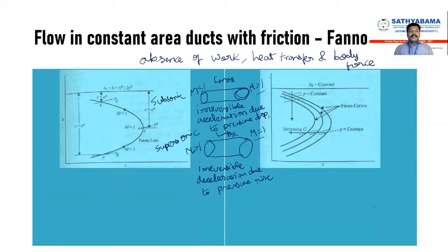So as per the energy equation, H0 is equal to H plus C square by 2. Here I am considering velocity as C, a notation for variation of flow properties. We are just changing the notation of velocity to C, right? So your H0, the total enthalpy of the pipe, is said to be constant, which is nothing but static enthalpy plus dynamic enthalpy. This dynamic enthalpy will be C square by 2, right? So everybody knows it. This is your energy equation, right?